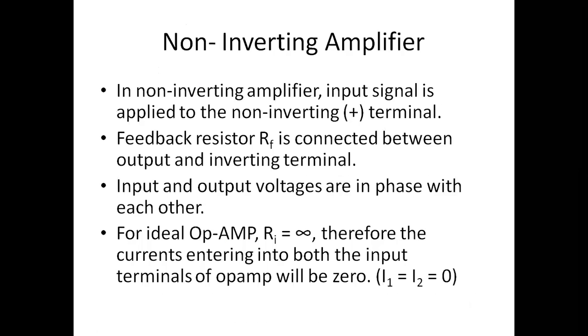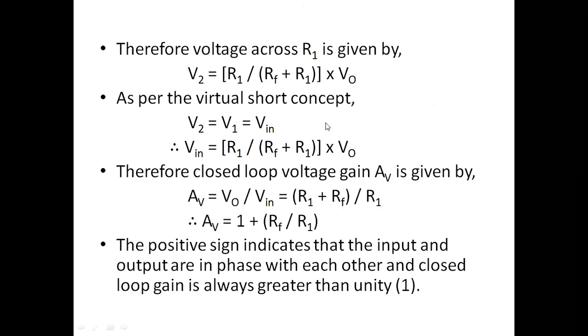voltages. So now we are supposed to study the non-inverting amplifier. What can we say about the non-inverting? If you compare non-inverting with inverting, here we give the input to the non-inverting terminal, and the output signal will be amplified, but it will not have a phase difference with respect to the input, because here we are connecting the input to the non-inverting terminal. Firstly, we will see the diagram.